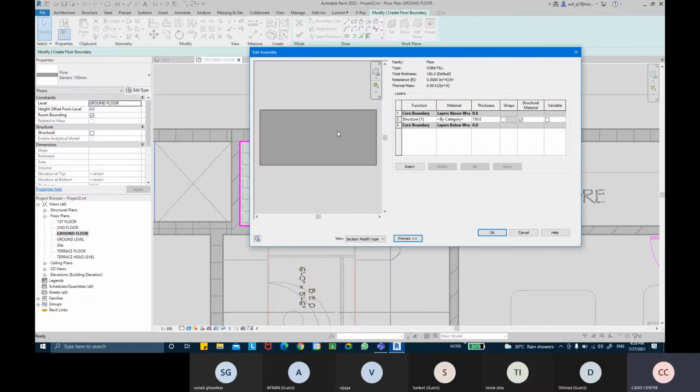One would be for the brickbat and the other layer would be for leveling the brickbats. We have a drop of 200 mm there. Let's say I'll give 165 mm of the brickbat and 10 mm of mortar. That would be a total of 175 mm.